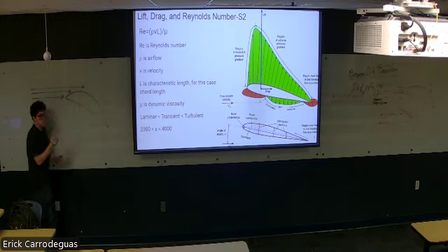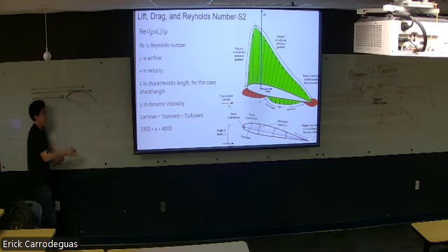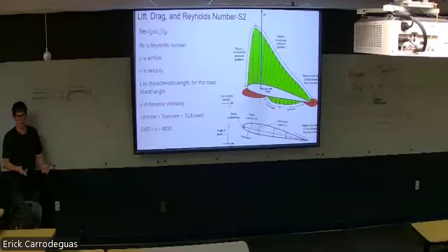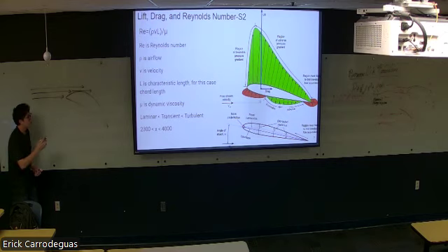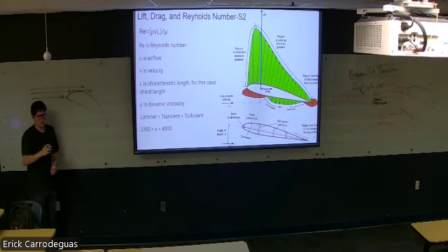So there becomes a point where all the air that's traveling on the top only reaches a certain part of the airfoil, let's say here, and doesn't reach anything here. When that happens, that means a stall is starting to happen. If you've ever seen a cockpit, for example, you'll see stall warning, stall warning, pitch down. Because once air is no longer traveling on the top of the airfoil, you've lost 2/3 of your lift and you're just going to start falling from the sky.